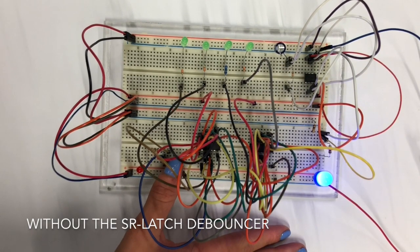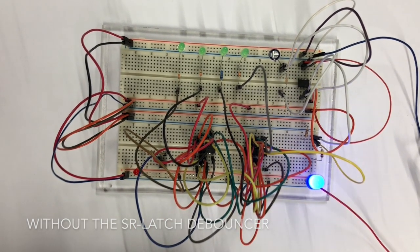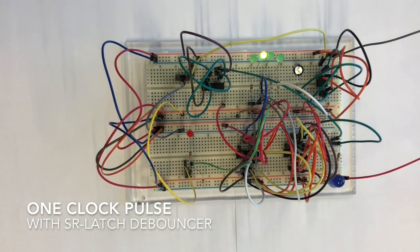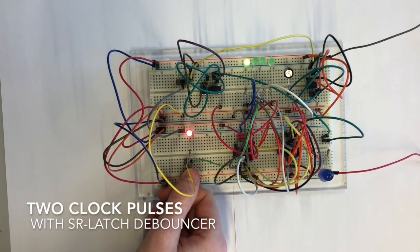When we connected the circuit, it did not work correctly, because for each clock cycle, we would get 2 pulses, as if 2 cycles had happened. We found that the rising edge of the 555 clock signal was noisy. Our solution was to feed the clock through a SR latch debouncer to clean the clock output before feeding it to the D flip-flops.